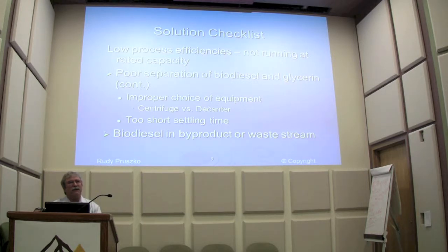No, centrifuges are a little bit more controllable than hydrocyclones. But for a rough cut, yeah, you could use it. If you use that for separation, either centrifuge or whatever, you want to err on the side of biodiesel going into the glycerin, because it's much easier to get the biodiesel out of the glycerin than it is to get the glycerin out of the biodiesel. It depends on your washing technique too.